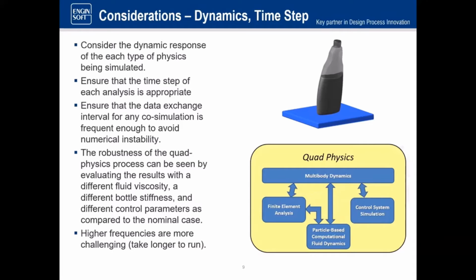And in the case of the particle-based fluid, the size of the particles determines the mass of the particles, and the frequency-type behavior in the fluid is going to be a function of those particle masses. So as the particles get smaller, the appropriate time step that should be used also becomes smaller. Anyway, all that should be looked at.